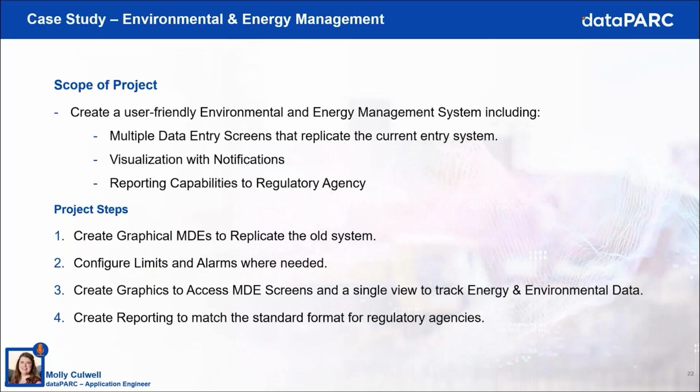And the steps went like that as well. We started off creating some MDEs and some graphical MDEs so that we could replicate the old system. And then we moved on to adding limits to either the process tags or the MDE tags. With those limits, we added alarms where they were needed so that they could send out notifications.